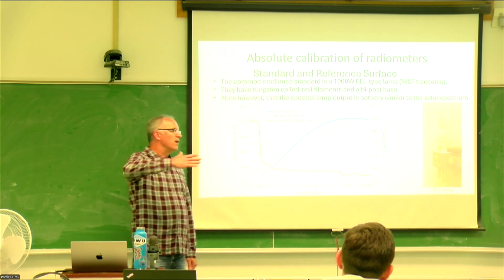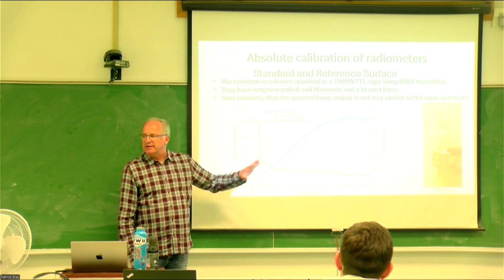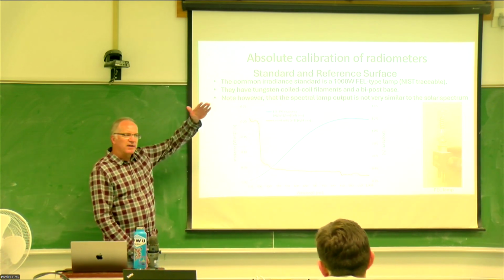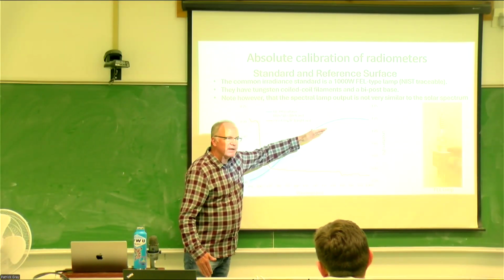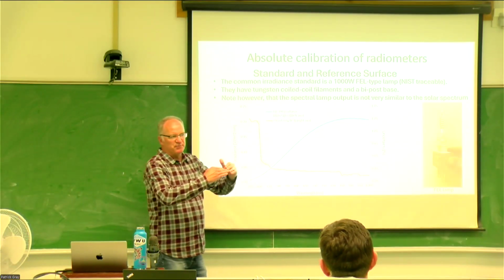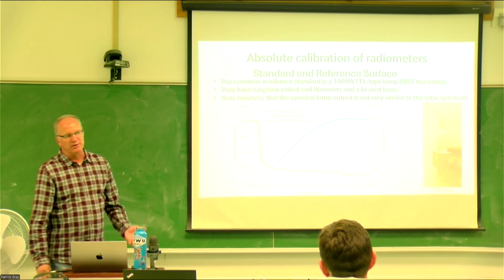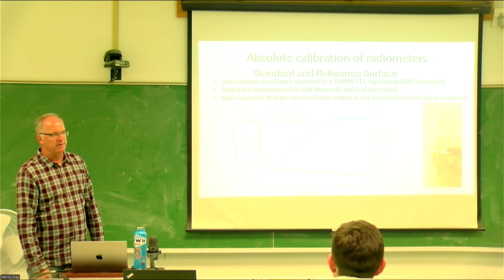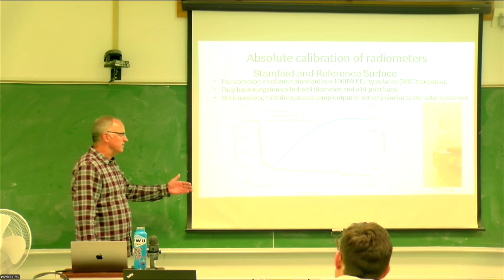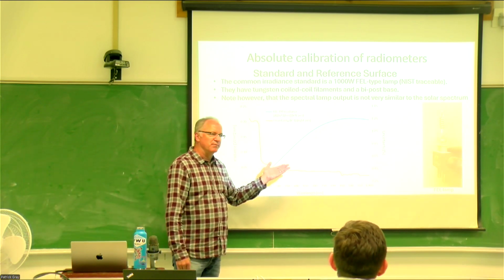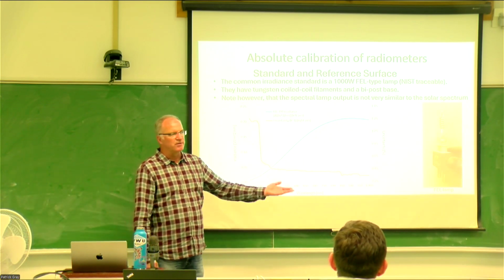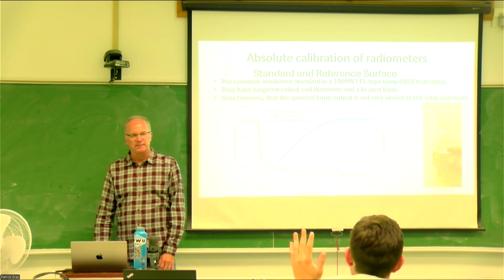And then when you get to around that 40 hours, does the output start looking weird? No, it's still pretty stable in its spectral output. It just starts drifting down. It starts getting dimmer and dimmer, but it's very slow. I mean, you can use these up to 200 hours. So what we usually use these for is not an absolute calibration, but if we're doing other characterizations, it's still a good light source for that.